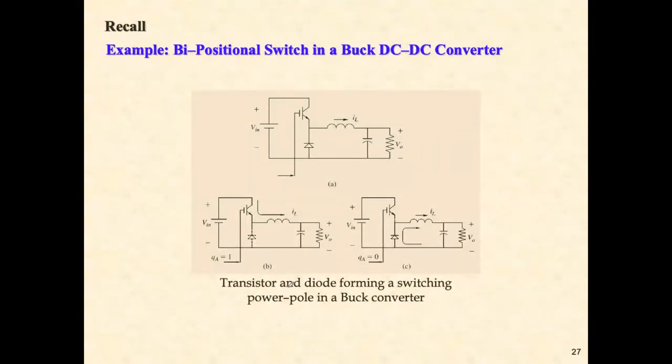Once again, we see this picture. We just went through the selection of the power transistor, and we also learned there are in general four types of diodes. Now for this application, for example a DC-DC converter, we should not use a line frequency diode, because the switching frequency needs to be really high. So now we should know how to select the appropriate transistor and diode for DC-DC converter use, or later other applications.